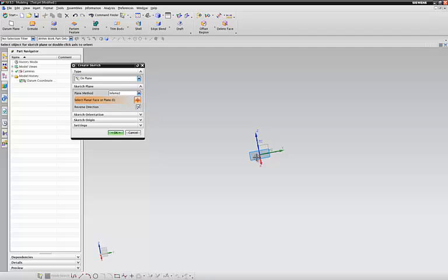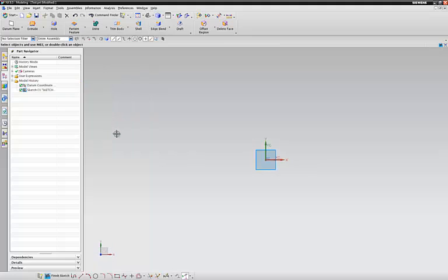As you can see, if you click the center mouse, you can rotate your object around. But for now, we'll click here and hit OK. And it will rotate us so we're looking down upon that location. This is a single line right here, or arc, or circle, or square. If we use this command, it'll continuously add more lines every time we click. And if we click and hold, it'll create an arc for us.